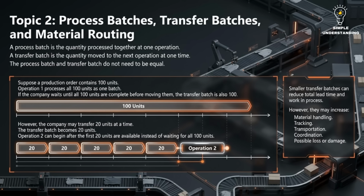Suppose a production order contains 100 units. Operation 1 processes all 100 units as one batch. If the company waits until all 100 units are complete before moving them, the transfer batch is also 100. However, the company may transfer 20 units at a time. The transfer batch becomes 20 units. Operation 2 can begin after the first 20 units are available instead of waiting for all 100 units.